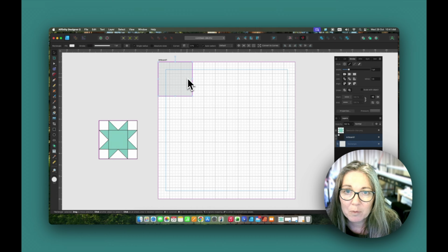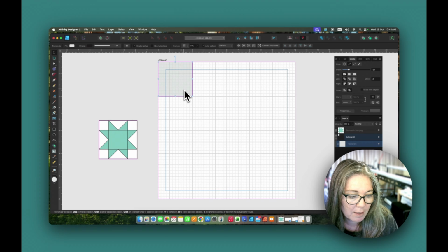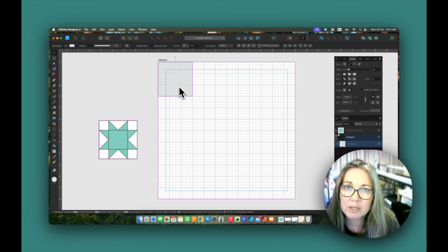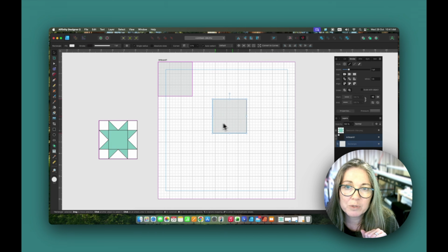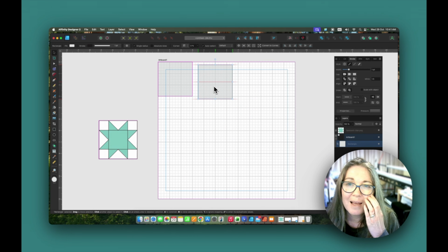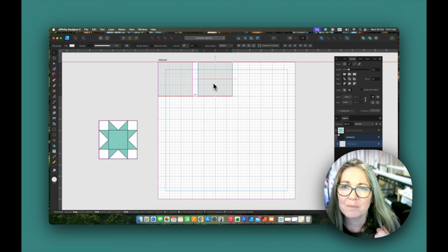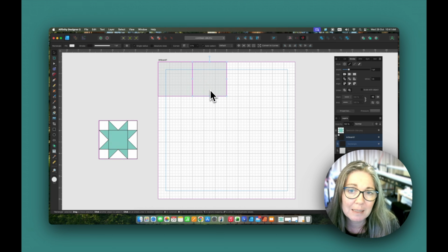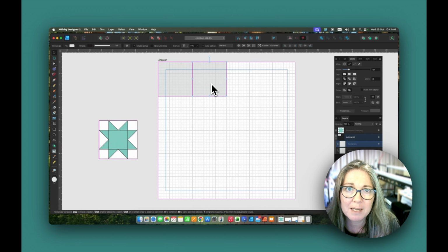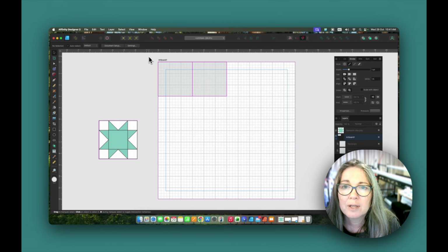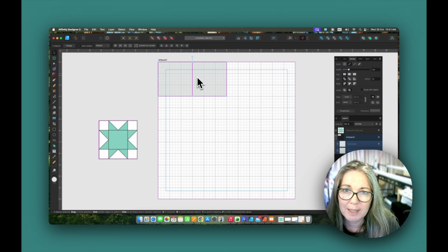Another thing you might want to be aware of: if you click on your square, we've got our square. I apologize, I have a Mac, so I'm using the option key. I'm dragging that with my mouse with my option key down. Now I've let go of my option key, it's all on the mouse, and I can situate that because I've got my snaps on. Easy, right? And it'll all be equal. I don't need to worry about it being out by a tenth of a millimeter or whatever. Then I'm just going to copy these two again, doing exactly the same thing.